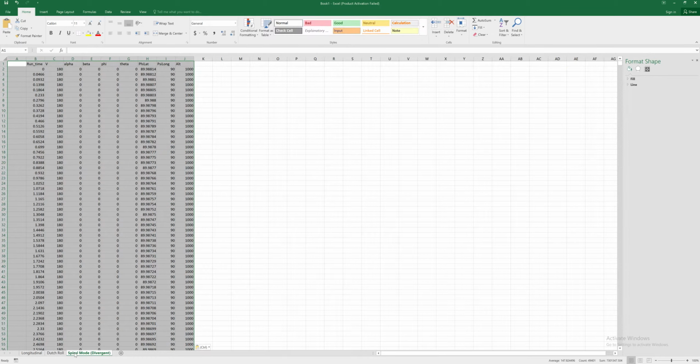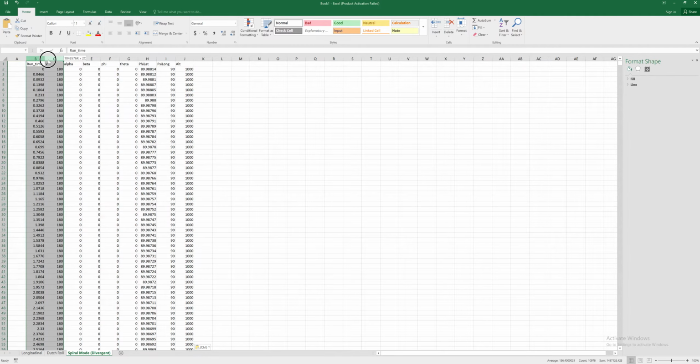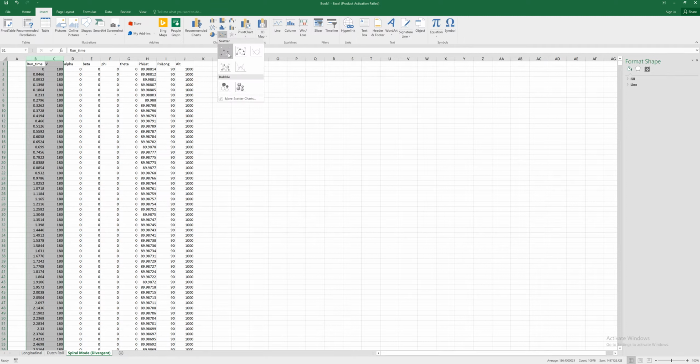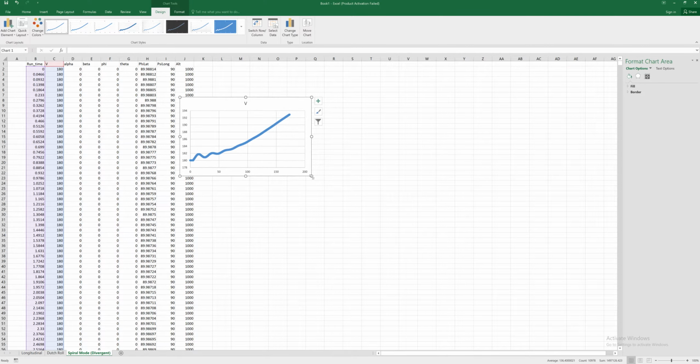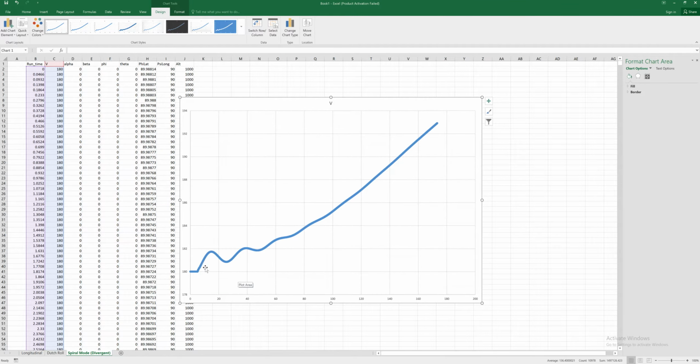Remember, the original version of this aircraft had a convergent spiral mode, and we changed one parameter so that it would now have a divergent spiral mode. So let's look at what happens here. Okay, so let's start with velocity. At first, this frequency that we see in velocity is actually the phugoid again from this disturbance. Again, a lateral disturbance will also excite the longitudinal modes, so that's what we're seeing here in velocity.